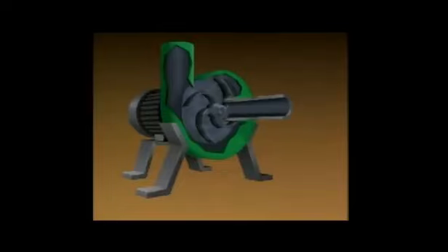During operation, the pump's driver rotates the impeller, creating centrifugal force that throws the liquid outward into the volute. The outward movement of the liquid causes two things to happen. First, it creates a reduced pressure area at the center, or suction eye, of the impeller. This area of lower pressure draws more liquid into the pump and provides a constant flow of liquid.